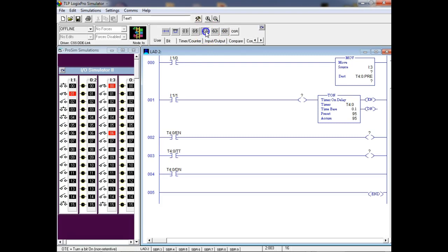Are you referring to what's in bits right there? Yeah, those are bits. They're either ones or zeros. One digit. So these guys right here are bits. You understand? And then we can come up here and assign this to output colon 2 slash 0. We can assign this to output colon 2 slash 1. And we can assign this to output colon 2 slash 2.